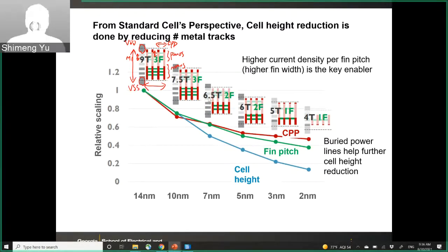So in the middle, you may have a half track. The design rule is, if you normalize that, it is about half track, because in the middle you may have a contact for the output. If you think about an inverter, you have input and output. So then you have an input contact and an output contact, maybe in the middle, somewhere here.